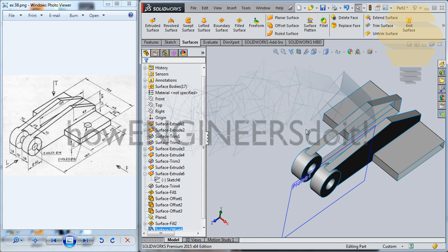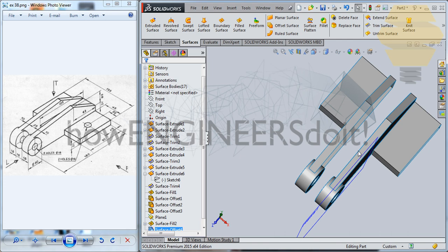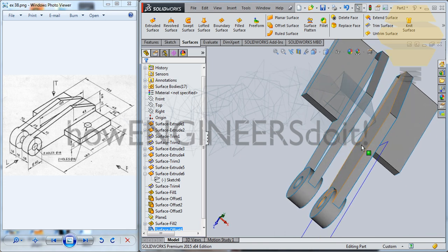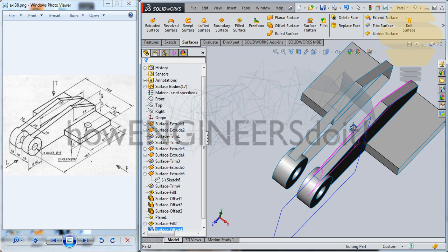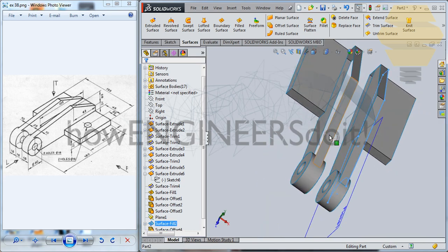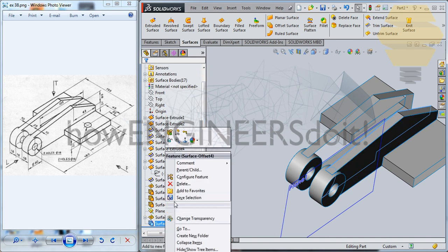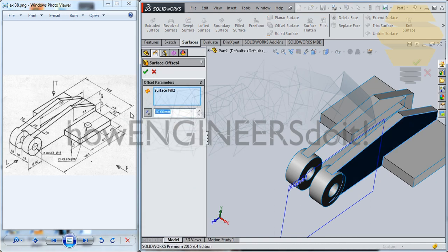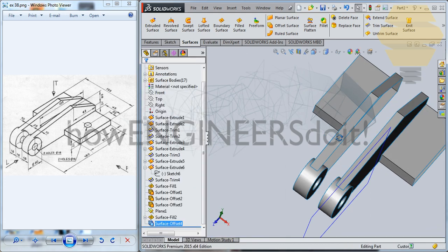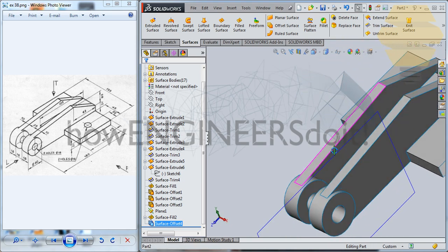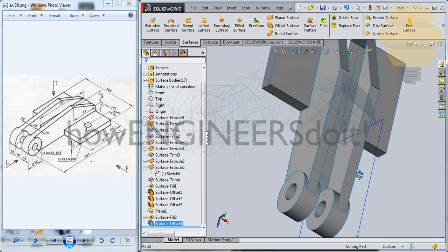Okay, so we'll give it like from this surface, because there's one more box or element that's gonna come over here, and this cutting won't be of that size. So what I would do is I'll take the surface to the surface here. So the overall distance, we can take it from the drawing, so that'll be 25 plus 10, 35, 45. So just go ahead to the surface here, edit, just give 45 here, so that that surface goes and stands at this point.